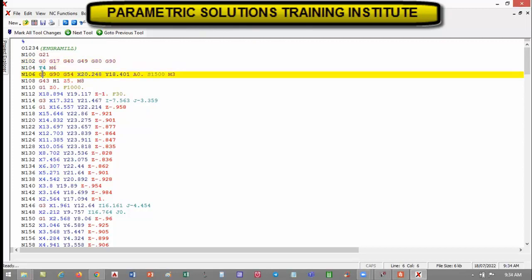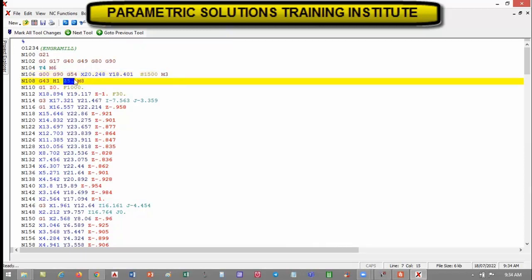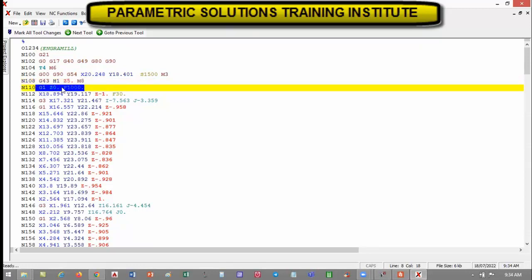Then from here the rapid traverse G00. Then absolute coordinate system workpiece zero setting on G54. Then X and Y A0 not required. And spindle speed M03 with S1500. Then tool height compensation, that is positive G43, H1 as per the tool. Then Z5 mm is above initially from the home position. The tool will come to Z5, and coolant starts here. M08 is coolant started.